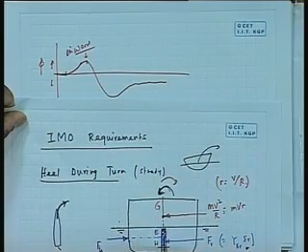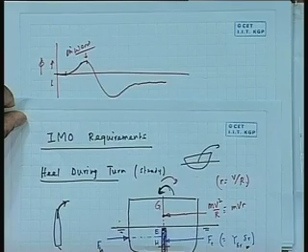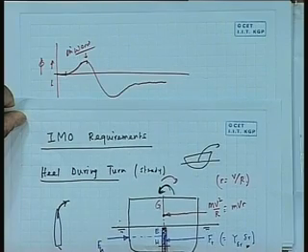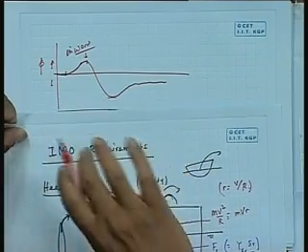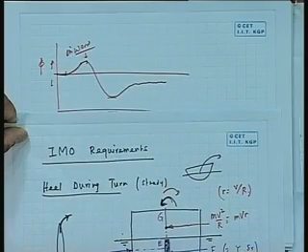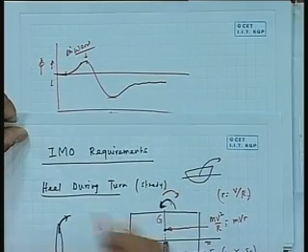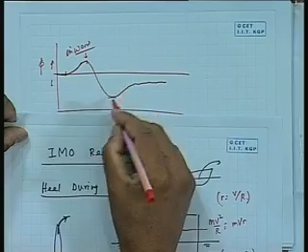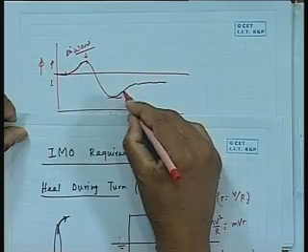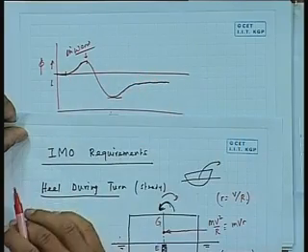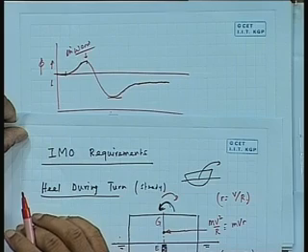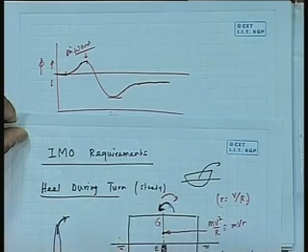Then there is a point when this Fh is large because it has both V dot and R dot as well as V and R. This is where it is more. That is in a transient phase. My total force is Yv dot V dot plus Yr dot R dot plus Yv V plus Yr R. So it is more. Then eventually the acceleration force reduces, so it comes down and comes down like that. So Fh will always dominate.